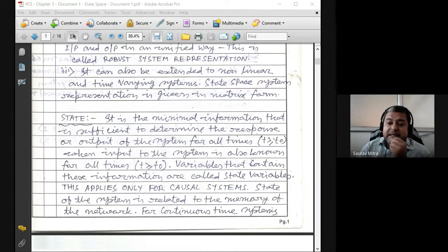Now somebody will say, or just for argument's sake, sir, why should I take only capacitive voltage as a state? I can take VR, the resistive voltage, as a state. You can take it. It is not wrong. Somebody will say, why do I have to take I as a state? I will take VL and VC as the 2 states.